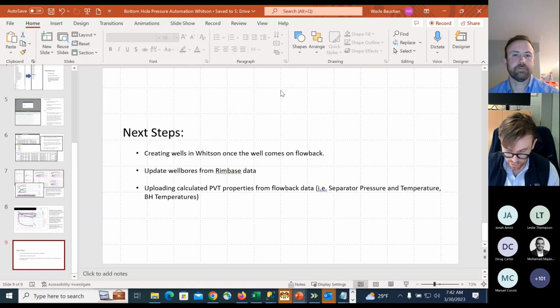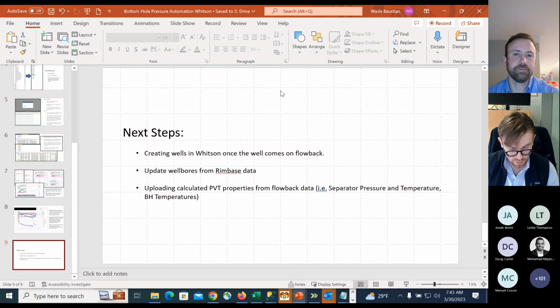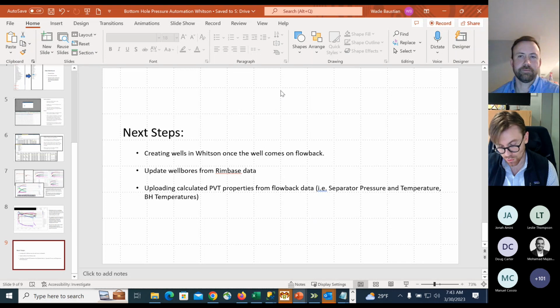And there's a follow-up question from Rohit there. Is there a way to automatically set up the PVT for every single well? The answer for that is yes. We do that quite a lot for most companies. What we do then, Rohit, at least for wells that are producing liquids, is we basically just use the average GOR of the first 30 days, or you can also suggest another type of logic.